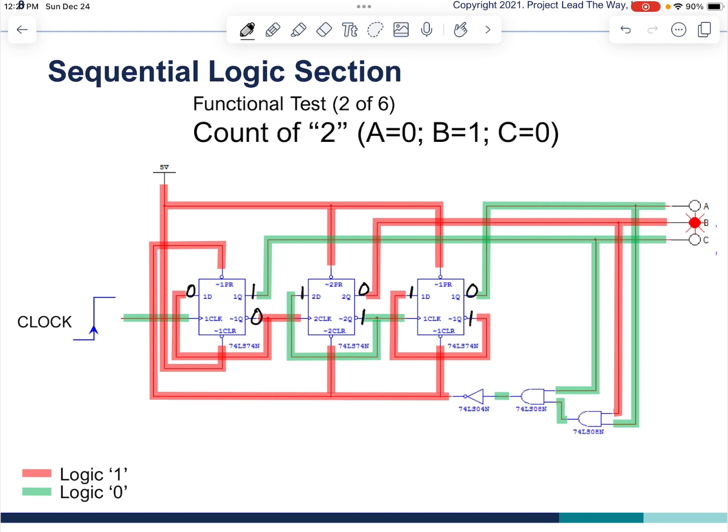So every time we have the rising edge of clock come in, that's my C, that's B, that's A, right? And this rising edge will fit into the clock of the C. It will pass this 0 to the output, right? So your 1 will become 0, therefore your Q naught will change to 1, right?